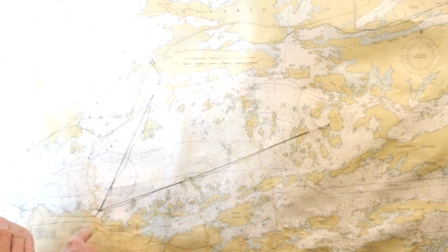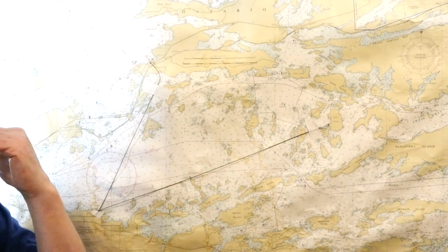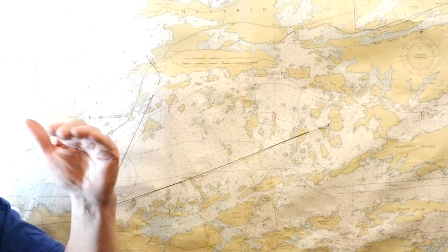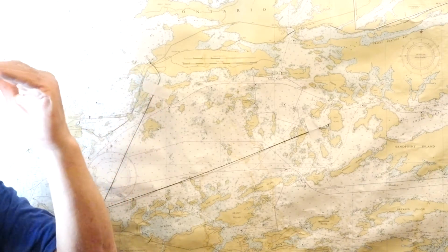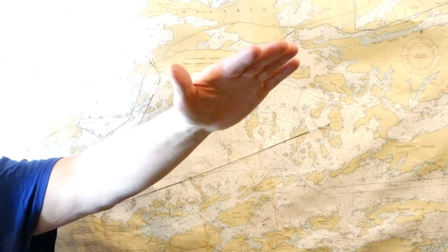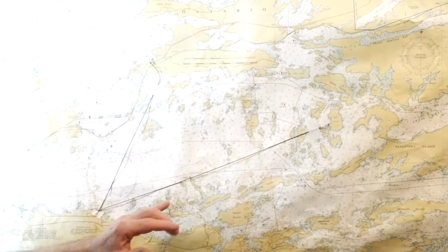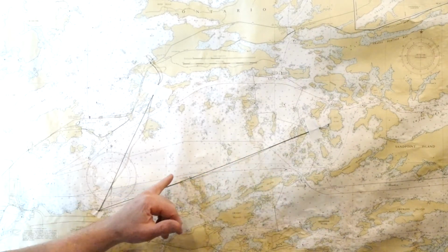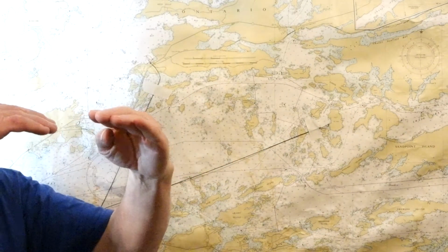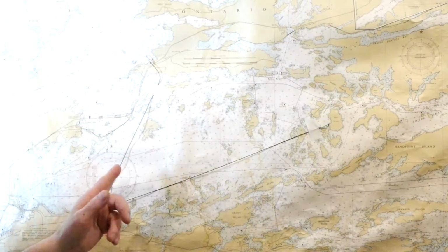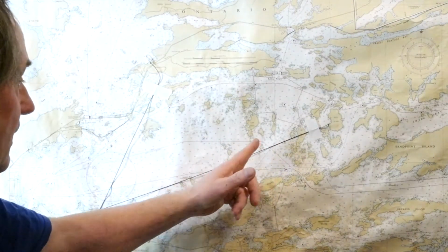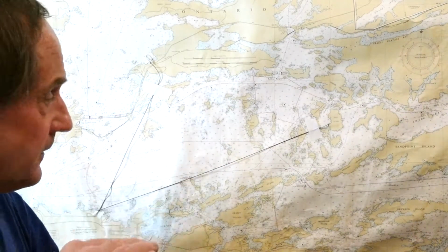We'll be establishing a tangent to the earth at about 12 to 14 feet above the ice, a tangent to that position shooting outward in both directions, and then set up targets on these poles so that they align with the tangent line.